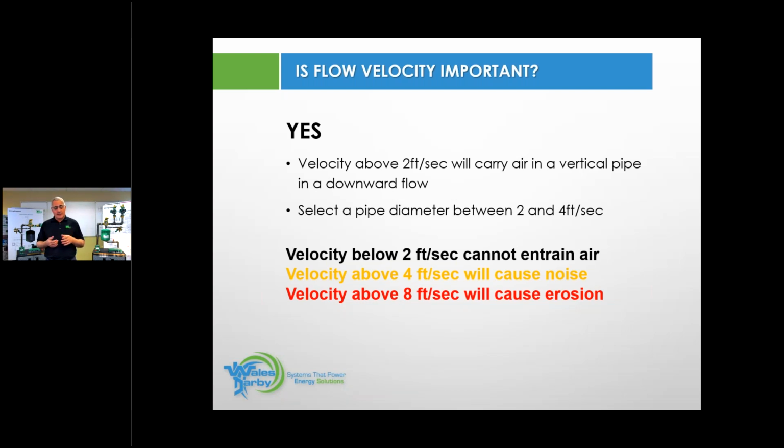What we show people is if I have a piece of 1/2 inch pipe and a 1/2 inch crimp fitting, that fitting has to fit into the pipe, and then the crimp band goes around it. Okay, so that fitting has to be smaller than the pipe. When we use our expansion fittings, Uponor does the ring that goes over the pipe, and then the fitting itself is bigger than the inside of the pipe. So we have to expand it with our tool and then put that fitting in. So it is a bigger fitting. It is a 30% flow rate. So there is a big advantage there.